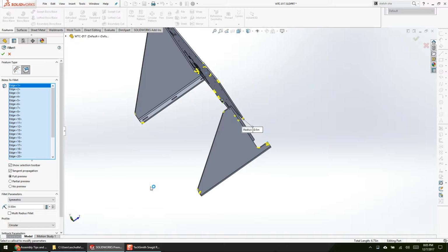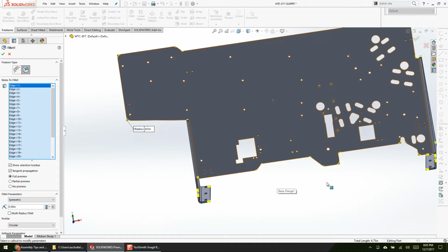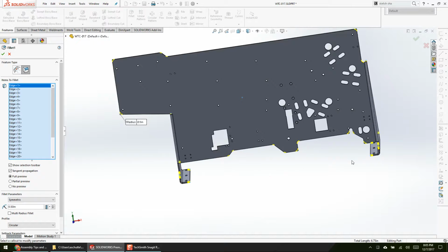Sometimes you have to do a fillet higher so you can linear pattern it or a few other things. But in this particular instance, you just fillet everything. Here it's because of laser. Your laser costs less and you get a better part if you have fillets. Lasers hate hard corners. They hate them. There's a large manufacturing explanation for that. But in this instance, I just do my whole design. It's done. We do the design review, talk to the customer. Everybody likes it. And I spend like 3 hours adding fillets to every imaginable part. And then I hit the go button and we build the machine.